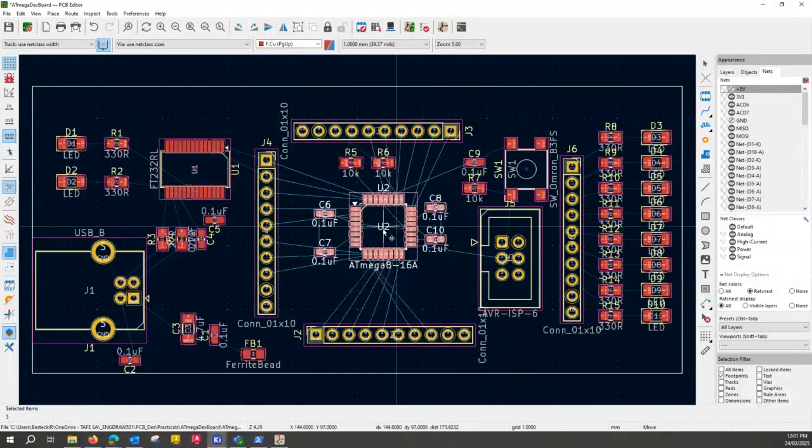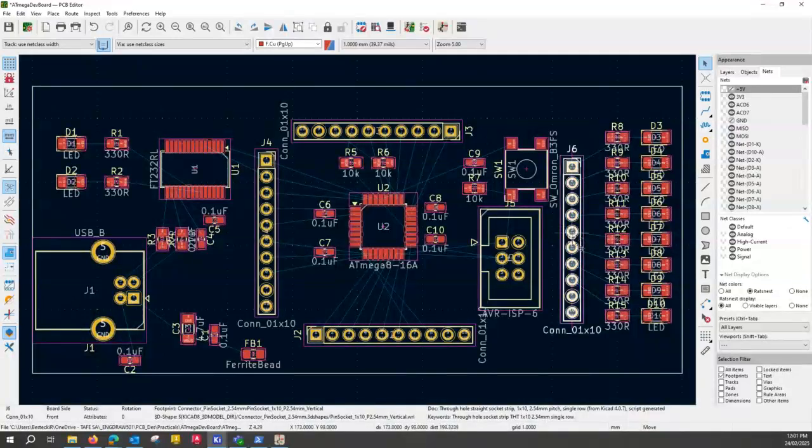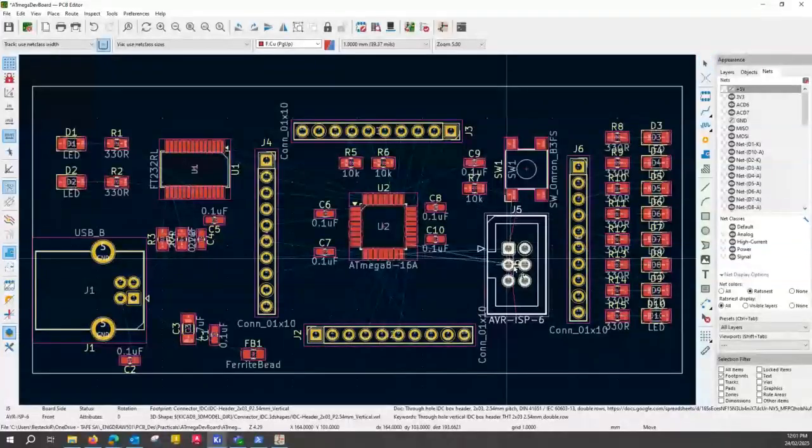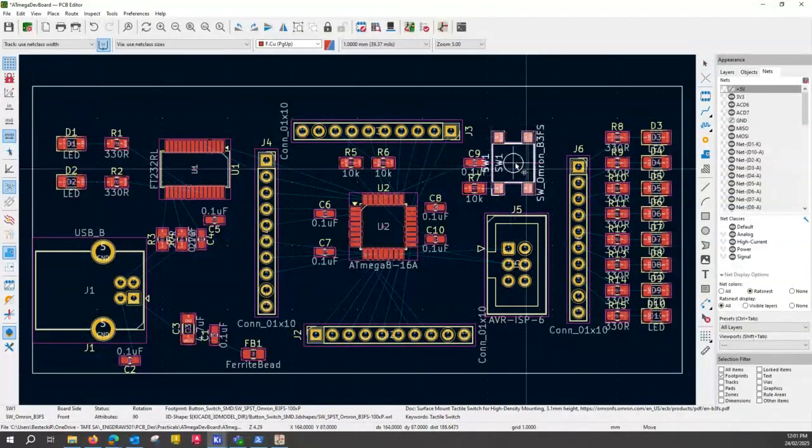Microprocessor, I'll probably move it across a little bit. I can squash this a little bit and push that connector in a little bit. That connector there, I can't see a need to have anything running in this area, so that's fine. That switch, can space it out a little bit. And those two, actually, when I think about it, I'll push that switch back.